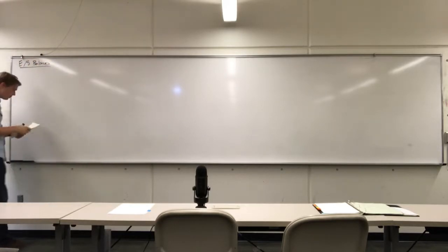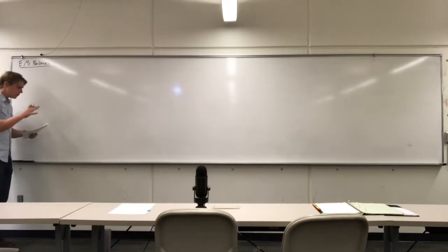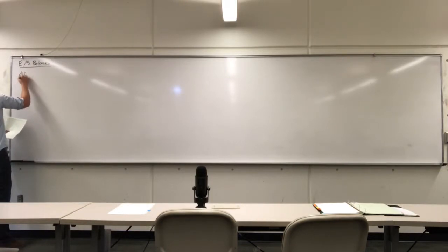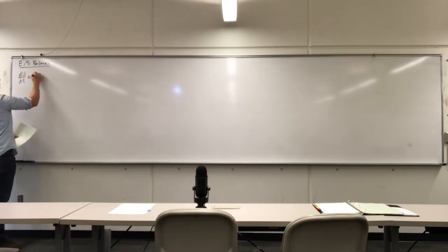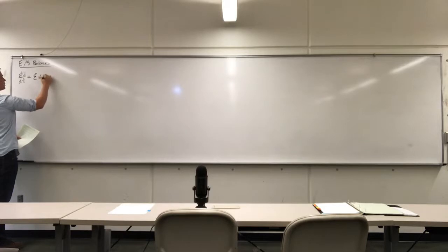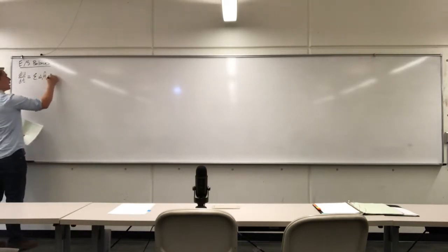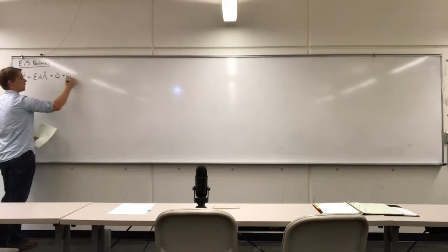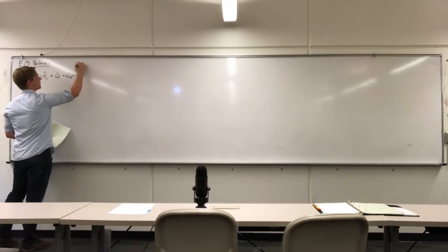So I'll do this for energy, but it's basically exactly the same procedure for the entropy balance. So the full form of the energy balance that we like to start off with in chemical engineering is this one here. The change in energy of the system with respect to time is going to be equal to how much energy enters the system in the form of enthalpy. We can put subscripts here, but if you see the summation, those subscripts should be implicitly there, plus the rate of energy in or out from heat, plus the rate of energy in or out from work. Now you can think of this as shaft work, and also we could do P dV dt. This is if it's a constant pressure.